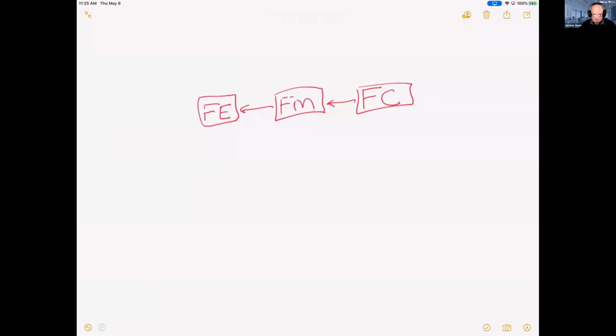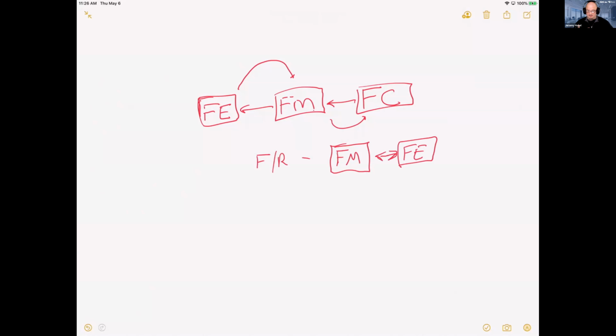This made logical sense, right? It's a two-way type of interaction, right? If I give you the effect, you should be able to tell me the mode. And if I give you the mode, you should be able to tell me the effect. But the piece that was substantially and significantly out of bed with the rest was the failure cause. The failure cause was out of alignment with the failure chain. And so in the AIAG VDA version of FMEA, the failure effect when it comes to DFMEA is always on the higher level design element.